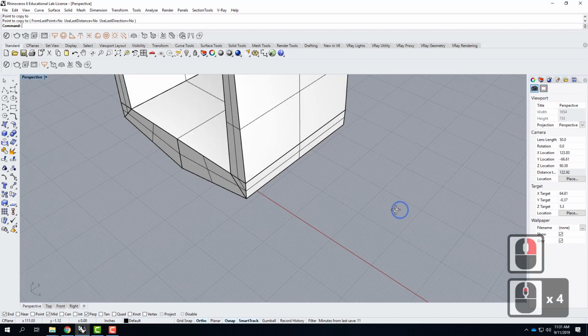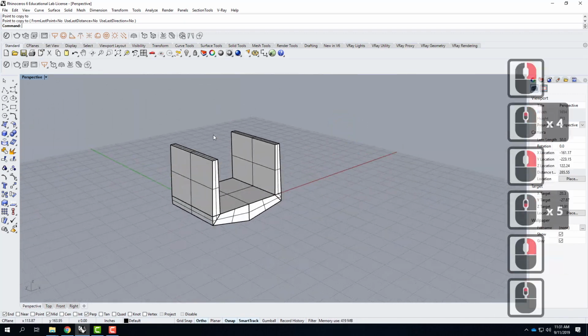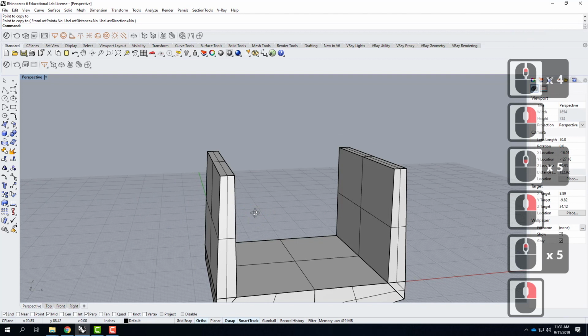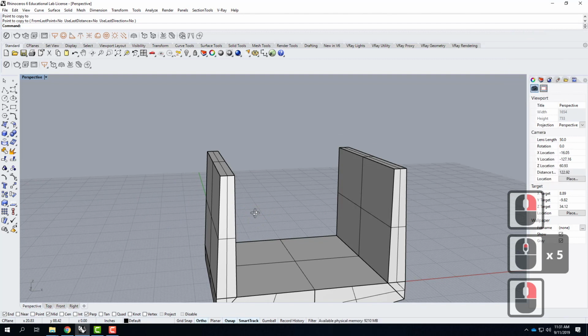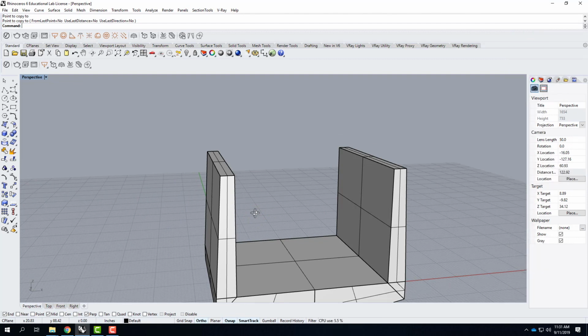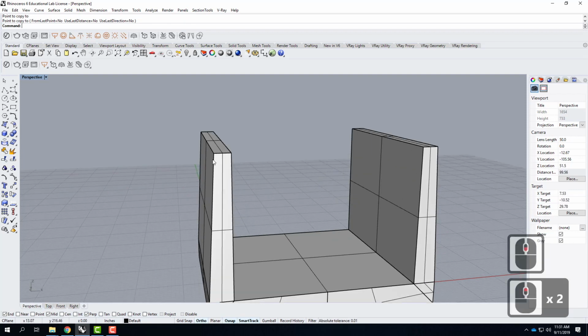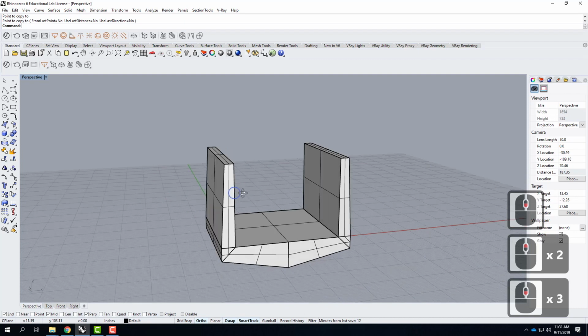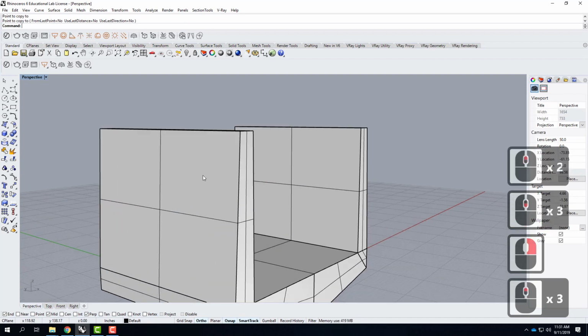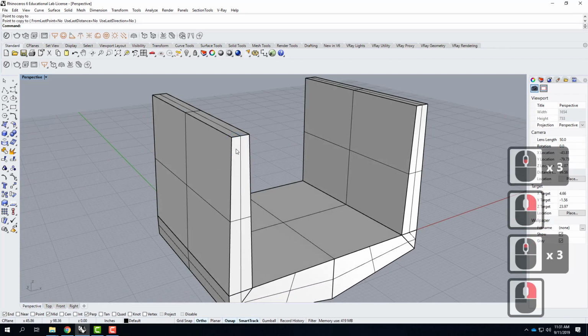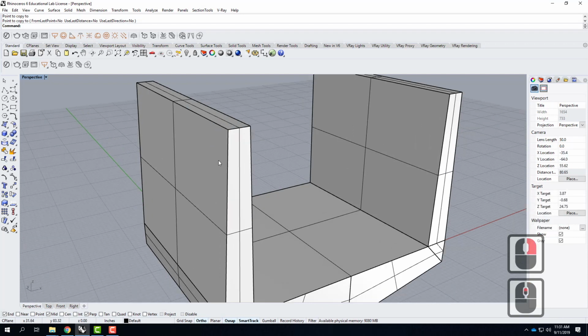So at this point, we want to add some detail to this shape. And so this is meant to be like a piece of a concrete bridge, like one of those walkways that goes over a freeway or something. And typically when you have this kind of a concrete pour, you're going to want joints between these segments. And there's usually a bevel at the joint. So there's a little bit of a chamfer. And so we're going to go through and chamfer these surfaces together.